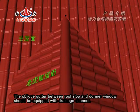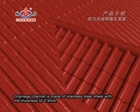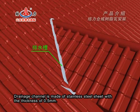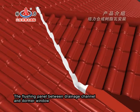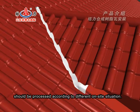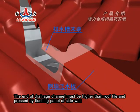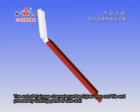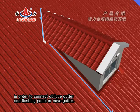The oblique gutter between the roof slope and dormer window should be equipped with a drainage channel. The drainage channel is made of stainless steel sheet with a thickness of 0.5 mm. It is fixed on the purlins of the two-slope roof before the installation of main tile. The flushing panel between drainage channel and dormer window should be processed according to different on-site situations. The end of the drainage channel must be higher than the roof tile and pressed by the flushing panel of the side wall in order to connect the oblique gutter and flushing panel or eave gutter.